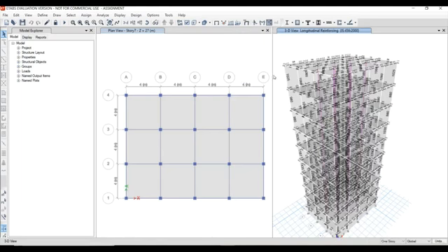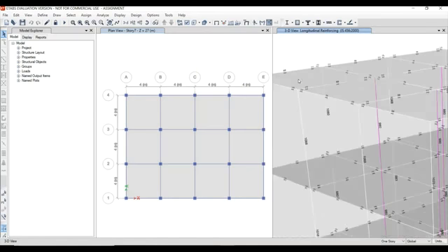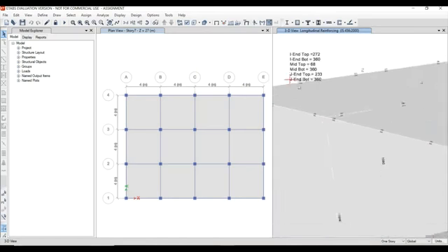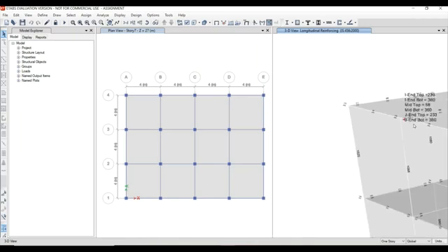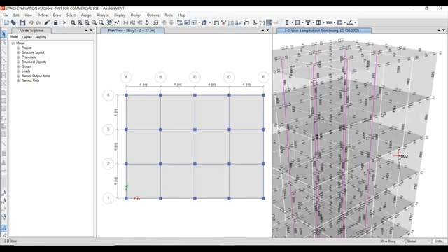Now design is over. So now you can see the design values or the reinforcement values as shown in the model, 1025 for this column as reinforcement bar. And here the top end reinforcement is 272 and bottom end reinforcement is 360, middle top is 68, middle bottom is 360 and so on. So you can have the detailing and reinforcement bars of each and every column and beam.